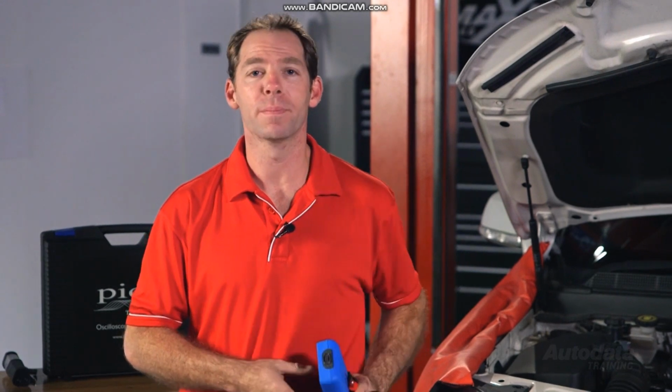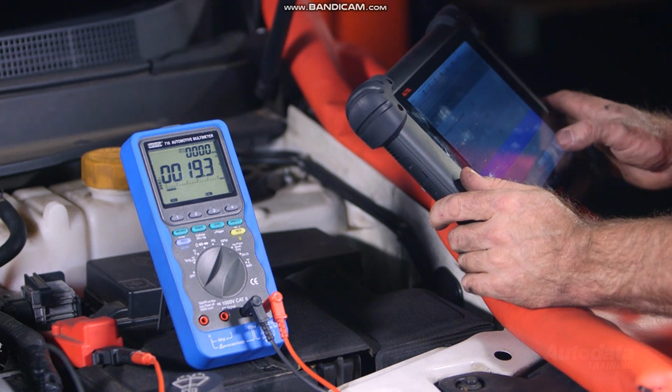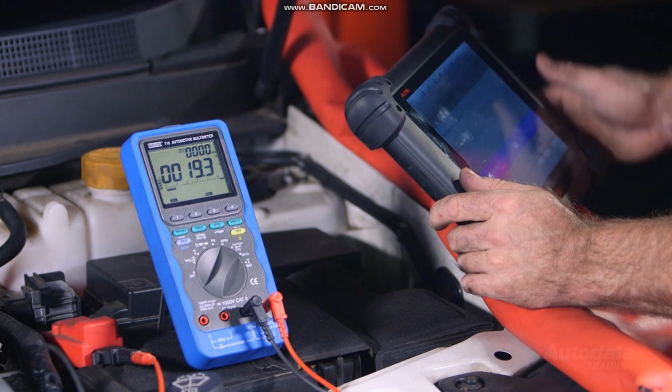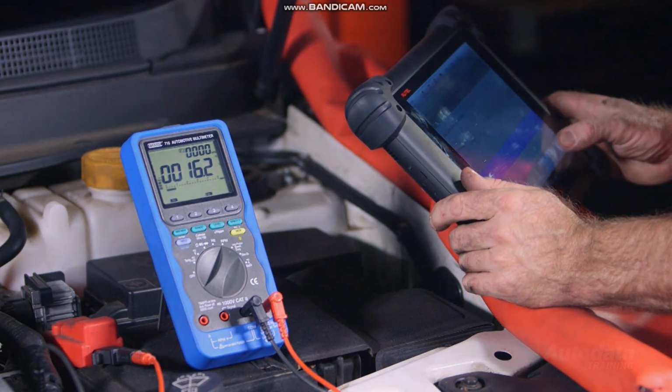If you don't have an oscilloscope, then this test may be carried out using a multimeter. With the meter set on duty cycle, connect one meter lead to battery positive and back probe the control solenoid low side circuit with the other. Using a scan tool, command the wastegate control solenoid to maximum and back to minimum. The meter should reflect the scan tool command.